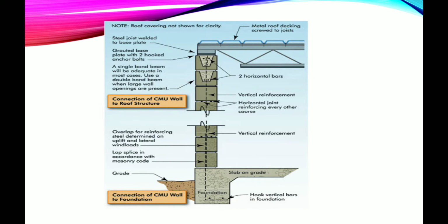This figure illustrates load path continuity of the structural system. Members are sized to accommodate the design loads, and connections are designed to transfer uplift loads applied to the roof and the positive and negative loads applied to the exterior bearing walls down to the foundation and into the ground. The roof covering is also part of the load path. To avoid blow off, the non-structural elements must also be adequately attached to the structure.